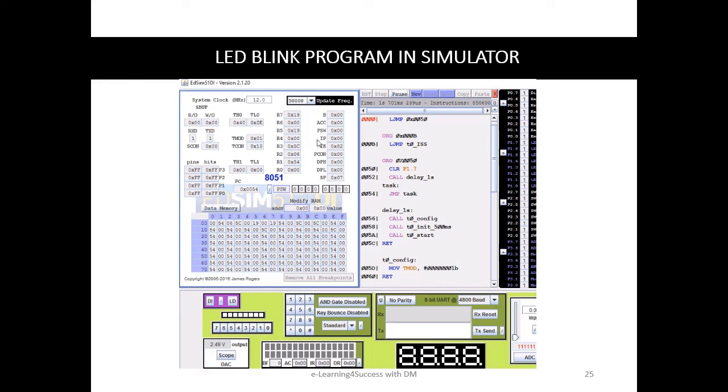In the previous lecture I had pointed out that the simulation times were exceeding what is expected from the delay subroutines we have written. This was because we skipped something there while we were rerunning the timer. This was given as an exercise for you to find out. But in this program we have rectified this. So you will see that the error observed through the simulation time in the previous lecture is absent here. So what was that error that we have rectified here? Think. This explains how slight modifications in the algorithm drastically modify the output obtained.